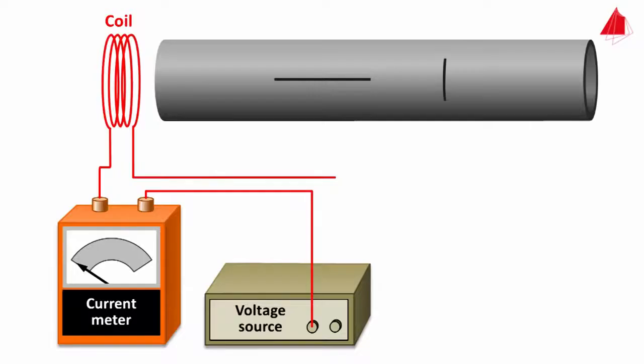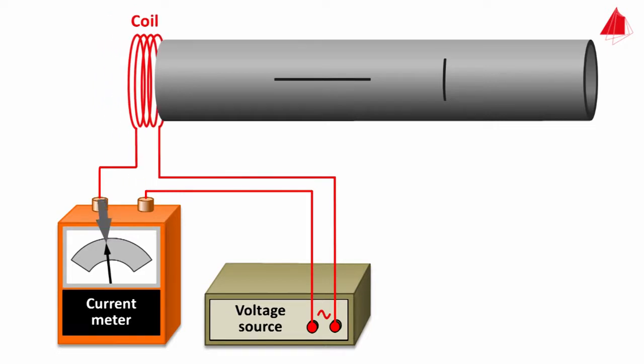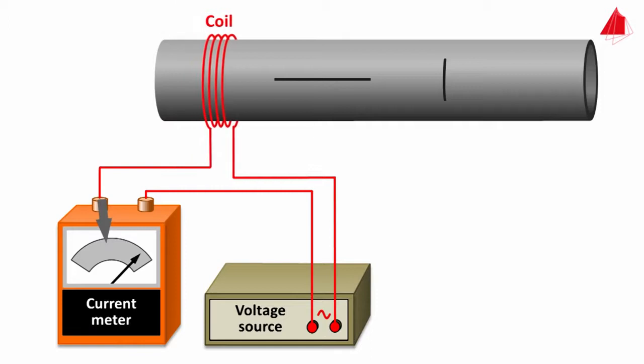The animation shows the physical background. Low current consumption as long as the coil is still far away from the tube. The reason for this is the undisturbed self-induction. Much higher current in a region where the tube is intact. The reason here is the eddy current, its own magnetic field, and the reduced inductance of the coil.